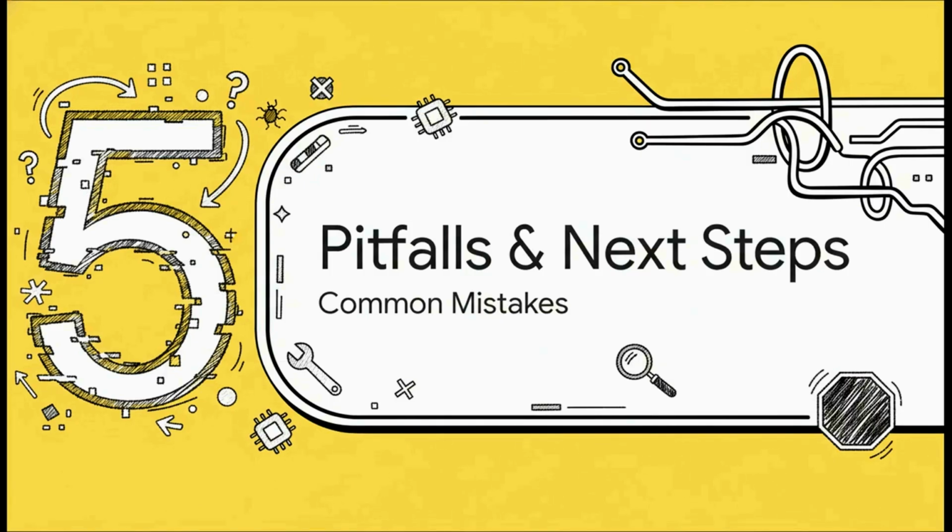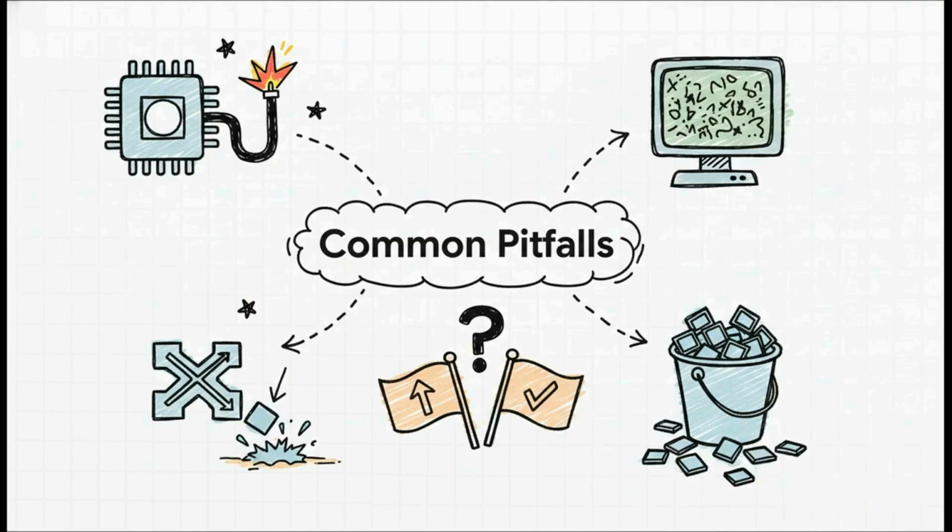We've covered a ton of ground, and just like with any low-level programming, there are a few classic traps you can fall into. So let's go over them real quick, so you can hopefully avoid hours of frustrating debugging. I've seen these trip up even experienced developers. Number one, by far, is forgetting one of those 3 clocks. Number 2, a simple math error in your baud rate calculation that just leads to complete gibberish on the screen. 3, misconfiguring the GPIO pins, especially forgetting to set them to alternate function. 4, an overrun error. This happens if a new byte arrives before you've had a chance to read the old one. And finally, like we just talked about, confusing TC and TXE and when to use each.